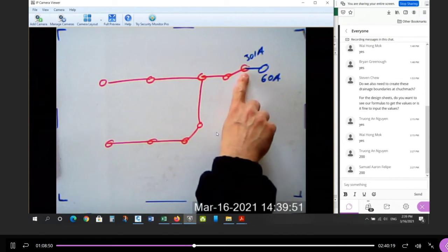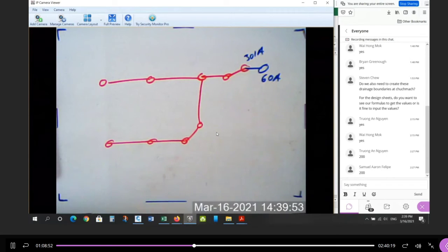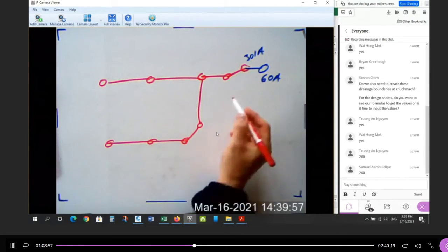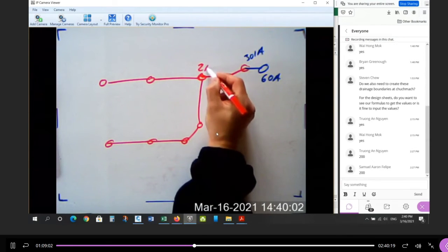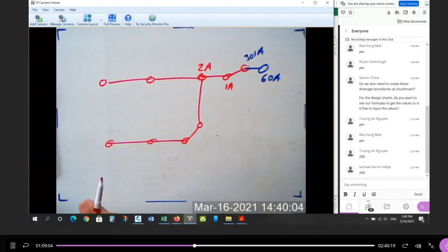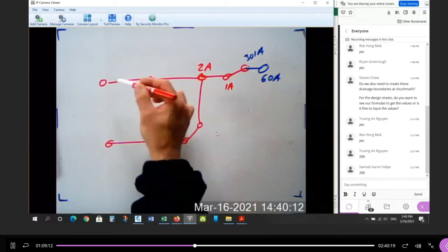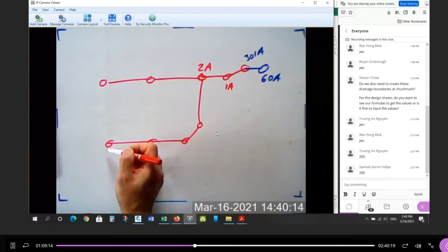This is existing on the road. This one's going to be moved perhaps. And now you have to number your own. Now start at the bottom and work your way up. Okay, so the next one, this is manhole 1A. When you get to this junction, this is manhole 2A. And then from there, you always go the shortest distance first, right? Or the smallest number of manholes first. So I've got 1, 2 here. I've got 1, 2, 3, 4 here.